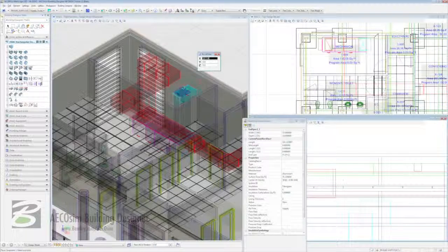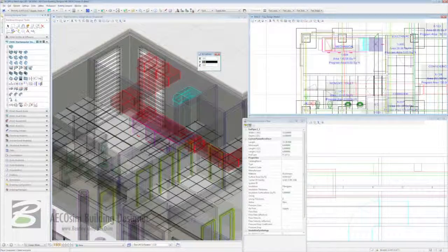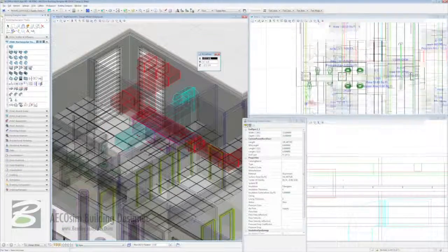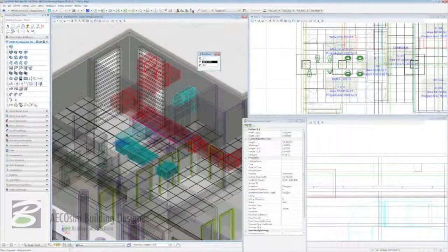In fact, what I'm going to do here now is hit the letter T for top. I'm going to take my ductwork and see my top here. I'm going to take it off this direction first, knowing that I can't go inside the electrical room. You can see that the vanes and the radial throat is there. I'm now going to come across here, pressing enter to keep that run going. Place that in there like that. And now if I scroll up or scroll down in my top view here, we're going to project this into the corridor here like that.